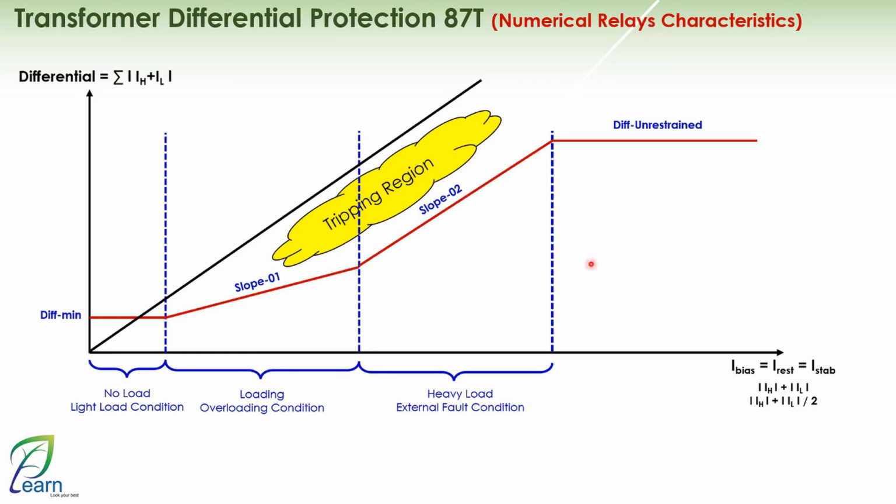But when does this apply? If the bias is the algebraic sum of the currents, not the algebraic sum divided by 2, because if it is divided by 2, it will be a different method with an angle of something and 60 degrees, depending on your equation, of course.